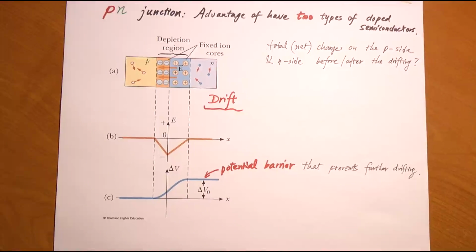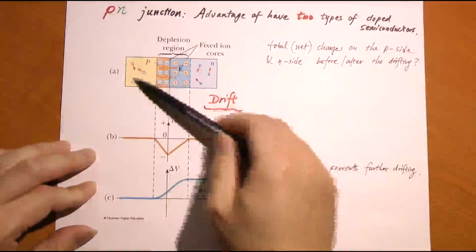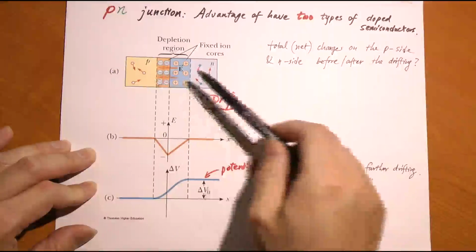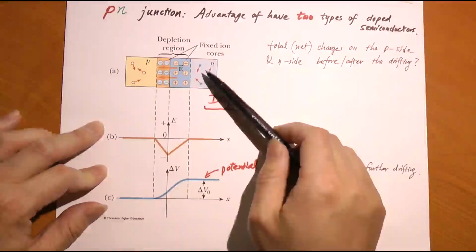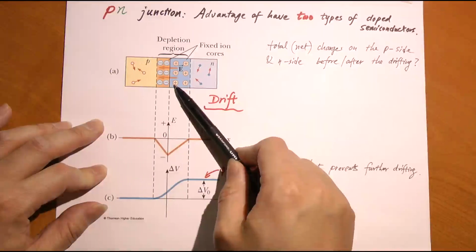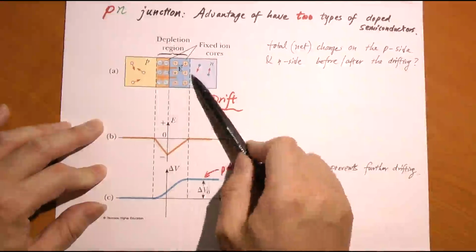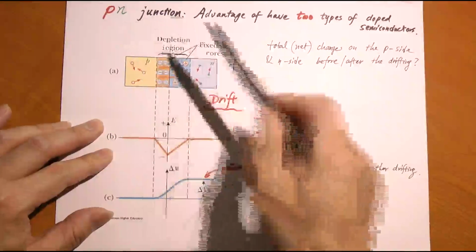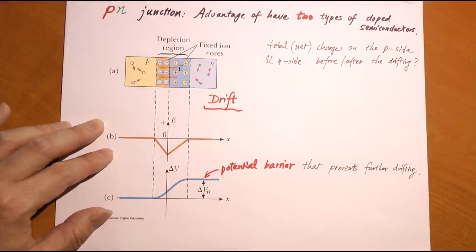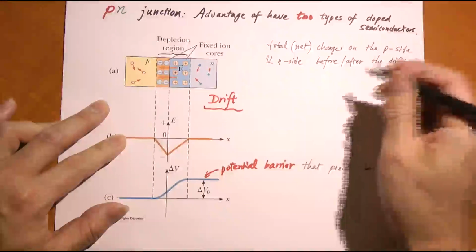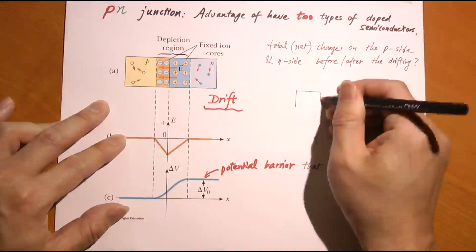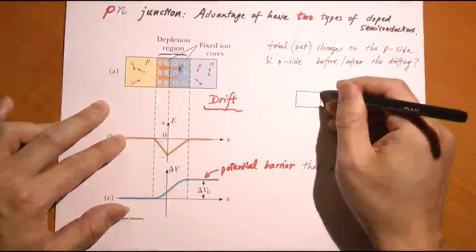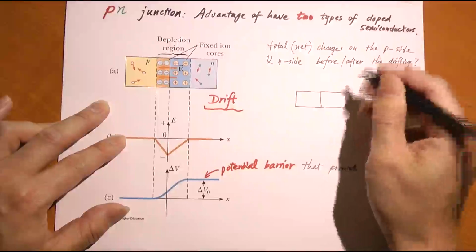So here we see what's called a p-n junction. This is when we put a P-type semiconductor and an N-type semiconductor, both doped with impurities, together in contact so that electrons and holes can hop back and forth. Okay, this is called a p-n junction. The p-n junction is one of the most important, interesting devices in microelectronics because of its interesting properties. Let's see. If I start from this is the P side, and here's the N side. Okay, P side and N side.